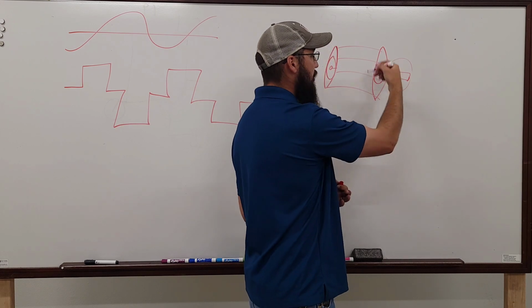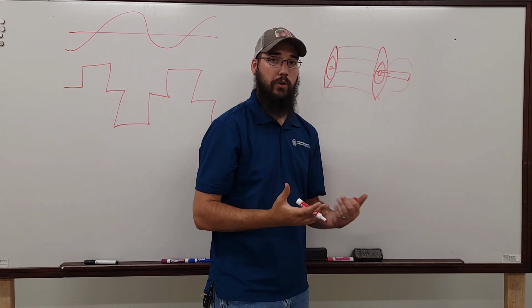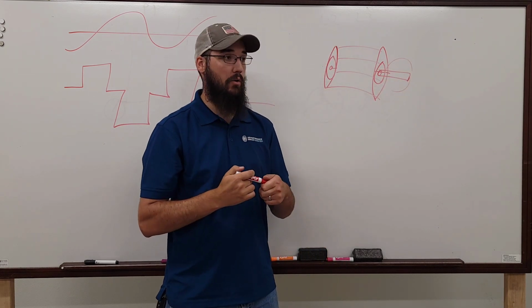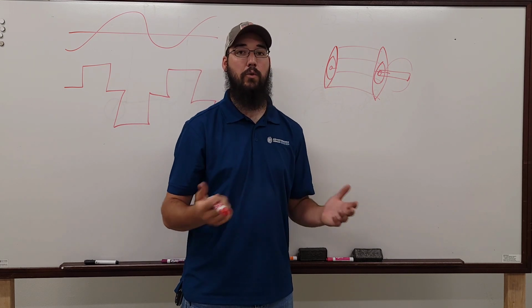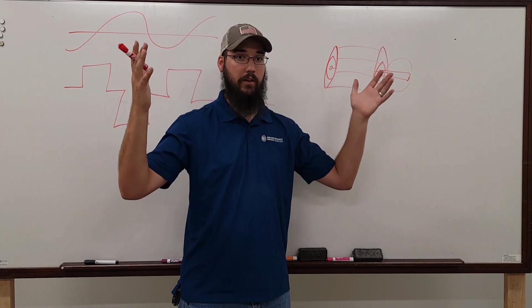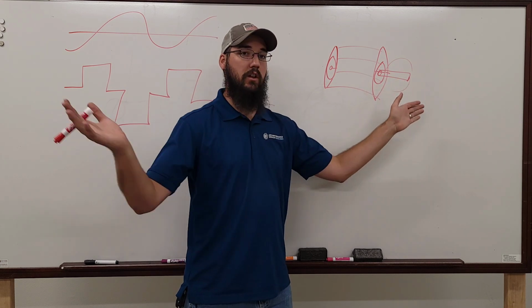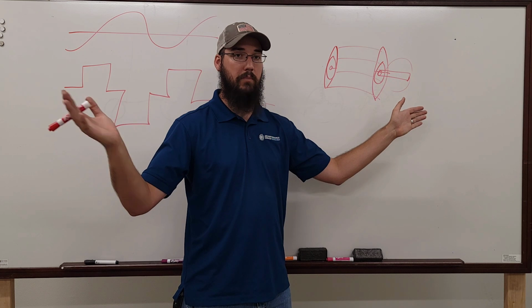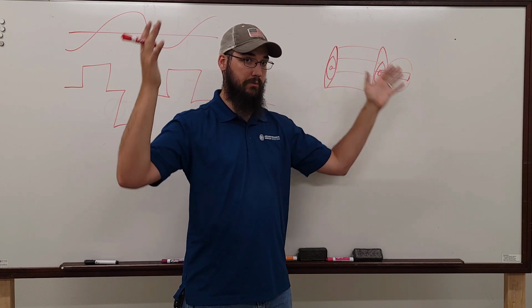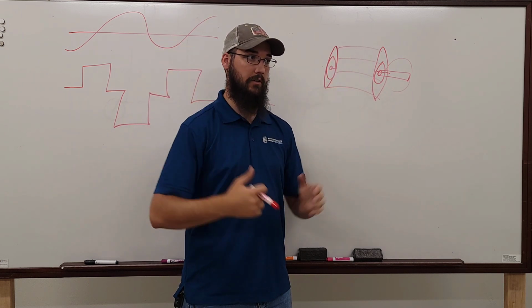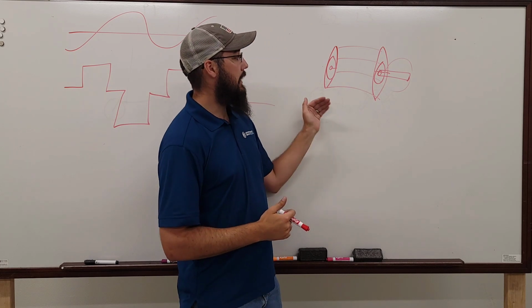The problem with that is the rotor doesn't have any other ground source the vast majority of the time, because how are we connecting motors to the load, right? What is the load? The fan, right? So how do we connect the motor to the load? Fan, belt, or if it's a pump, shaft or coupling, right? Isolated.